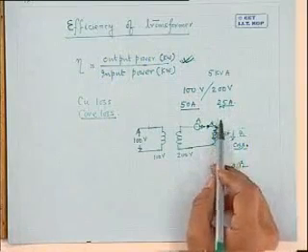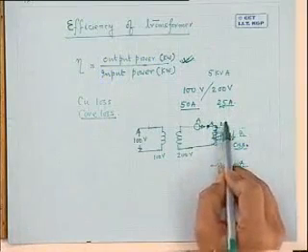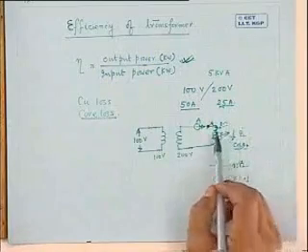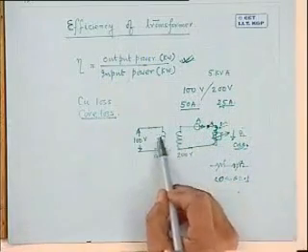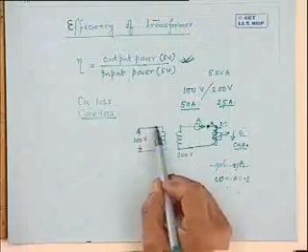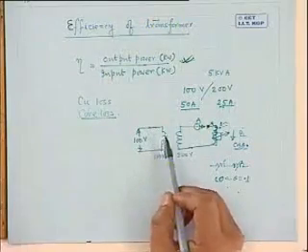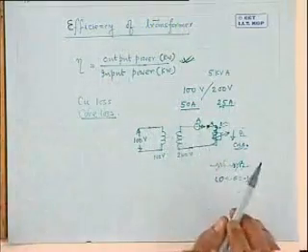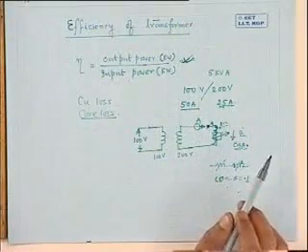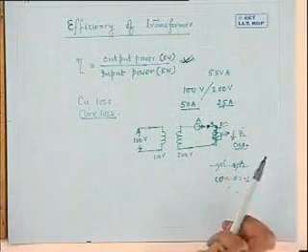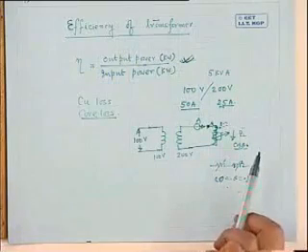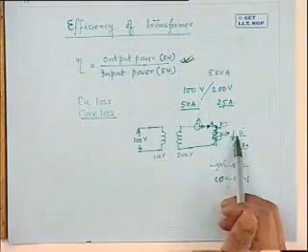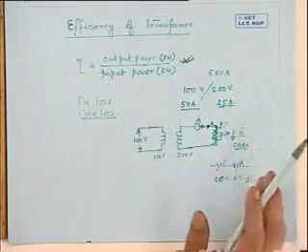How much XL should you connect? 200 divided by that should give 25. 8 ohm. Suppose you connect 8 ohm inductive load purely, 25 ampere will flow, and accordingly here 50 ampere will flow. I will say the transformer is fully loaded, loaded to its full capacity.